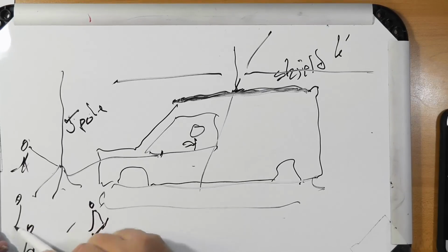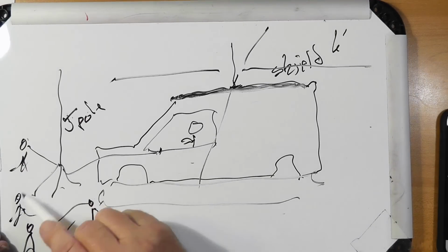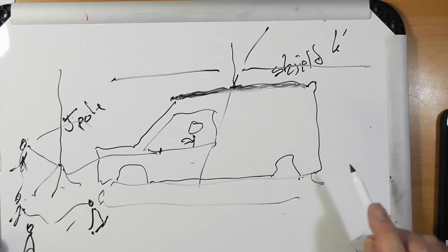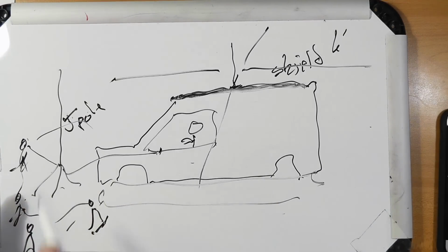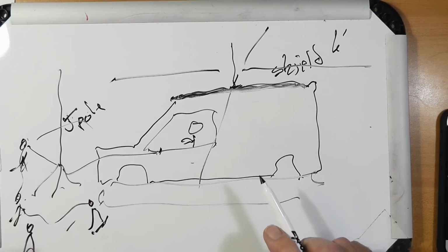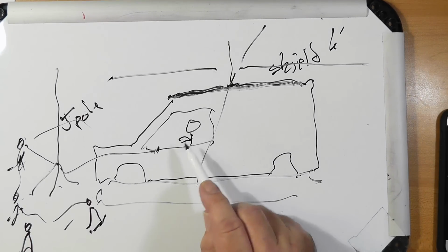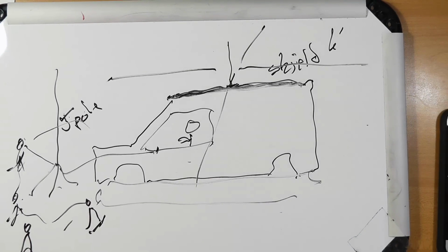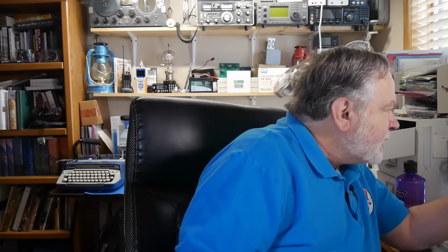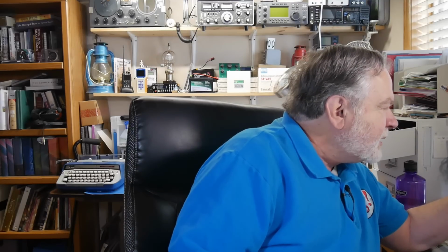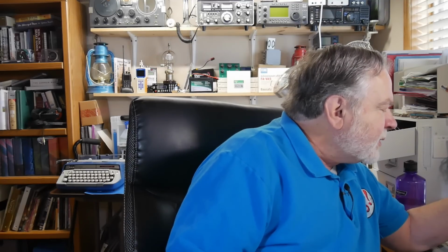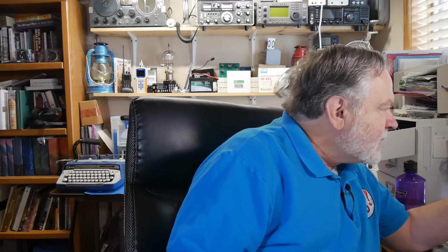You're going to want to put cones around this thing 6 feet away from it. Okay? And some sort of a do not cross kind of tape around it at 5 feet away from it. And then you want to be more than 5 feet away from that. Then you, in your controlled environment, are okay because you're actually okay within the uncontrolled environment here. All right? So you're in good shape.